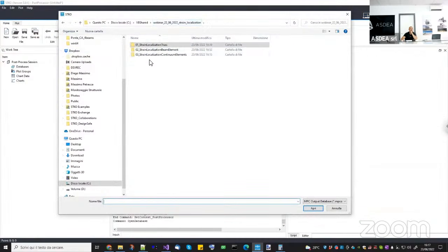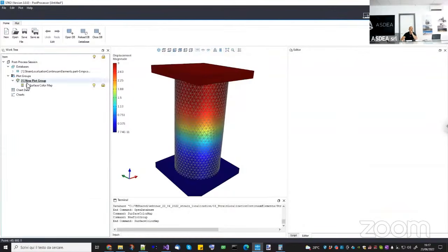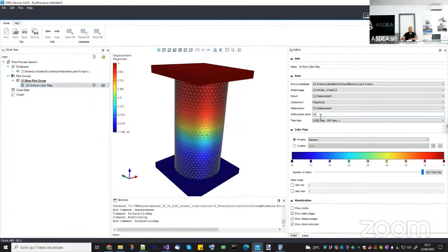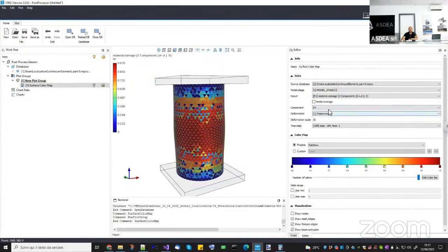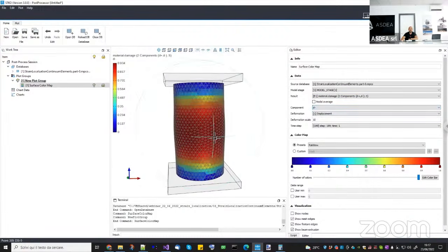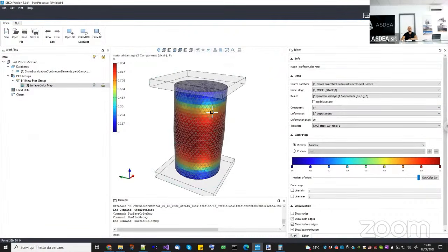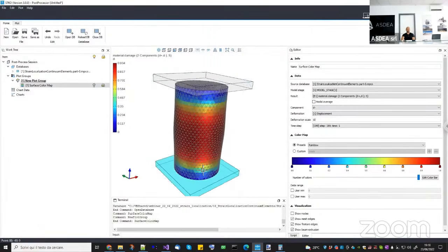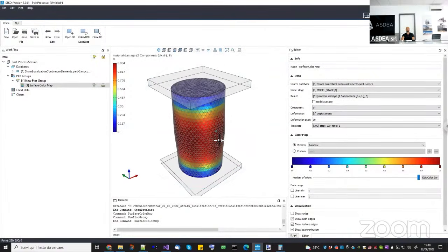So we go to the output of strain-localization. If I look here, the displacement seems pretty smooth. Okay, and if I look at the damages, I see a positive and a negative damage, which is very distributed. So I cannot see any crack actually. Why? Because the state of stress is pretty much uniform. Well, there will be a difference here at the top and here due to the Poisson effect, but it's pretty much uniform. So here we should use the same concept of assigning random imperfections.